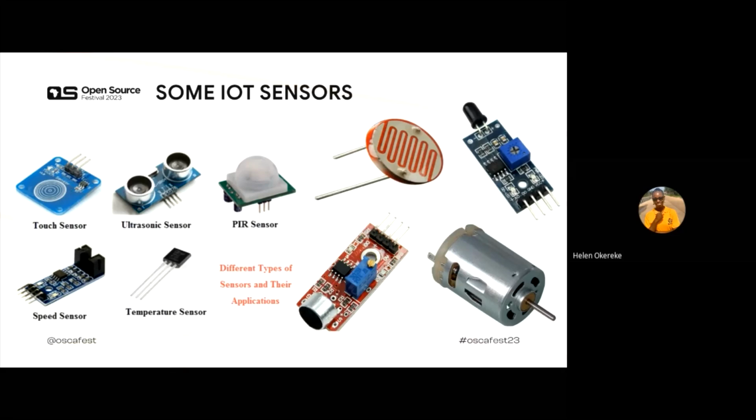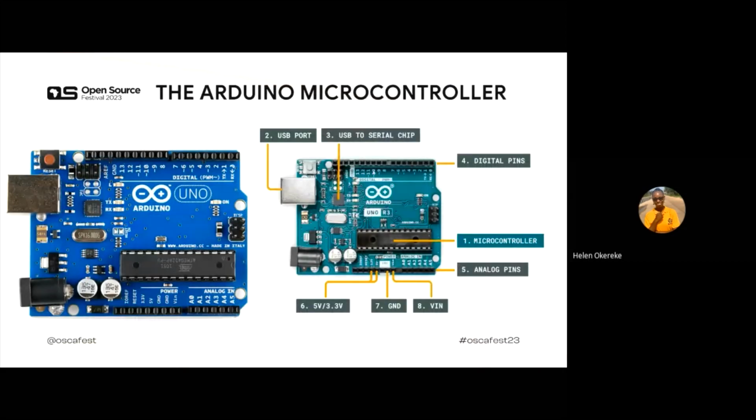Remember that once this motor is rotating, we need to control the speed. There are other things to control, but this is an output device. We need to decrease the speed, we need to increase the speed. It's not only high or low. So this is where the PWM comes in. If we want to connect that motor to the Arduino, we must connect the motor to one of the PWM pins. Are you getting me?